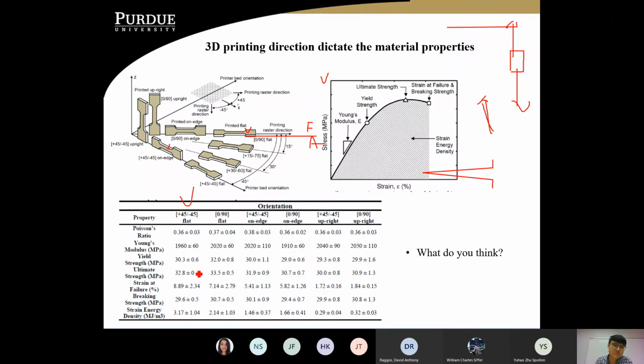So you would imagine at first that, printing the same material, why would the number be different? But here it basically shows the strength is completely different. Okay, 29, 29, 29, and then there's 32 over here. I haven't even mentioned failure breaking. So this basically gives us more of an idea. Okay, failure breaking, just focus on the number. So this is 8.89, right?